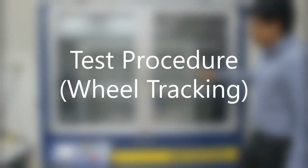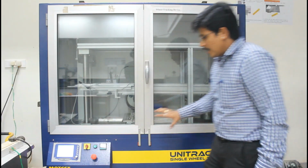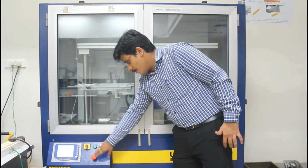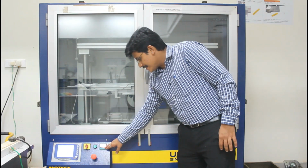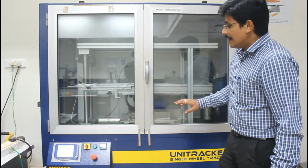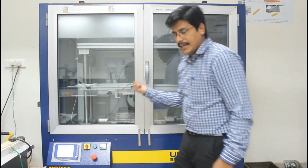Now this is the wheel tracking device. So you can see here the different parts of the tracking device. Now this is the control panel, right? The emergency button is power off, reset button, and this panel is used to set temperature. Now currently we have set for 16 degrees and now it is 31.6 degrees, right? And then there are different function keys which we can use to operate this particular wheel tracking device.